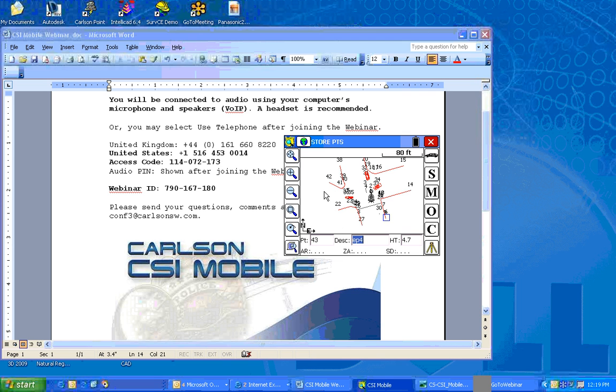And that might just be a multiple intersection. That might be correct. So that was pretty convenient. If you make a mistake in the field, you take a bad measurement, you see the results, you click the point, and you simply redo the shot. All this is stored legally into the RW5 file, the raw file for the project, which could be presented in court, and the points that are remeasured will turn into remarks. When you remeasure, your prior shots will be remarked out but not omitted from the RW5.